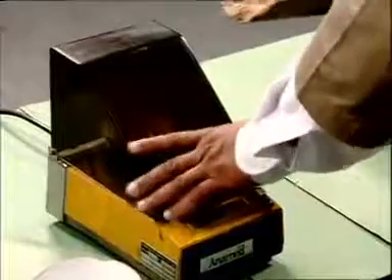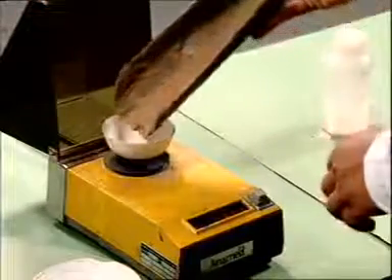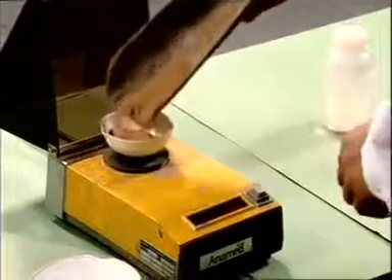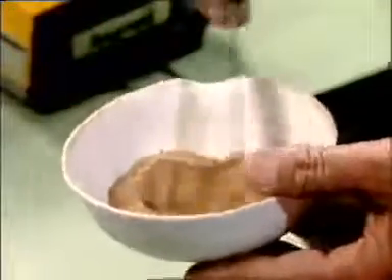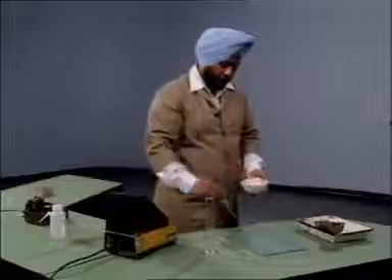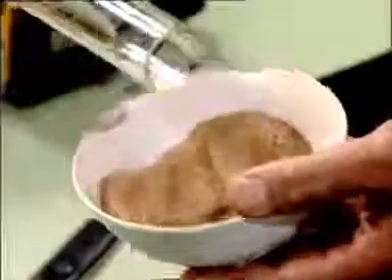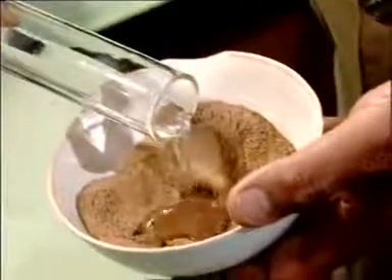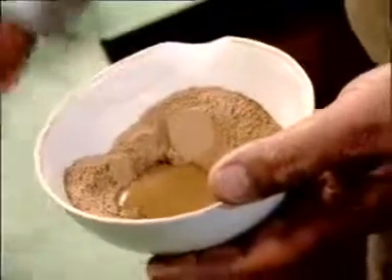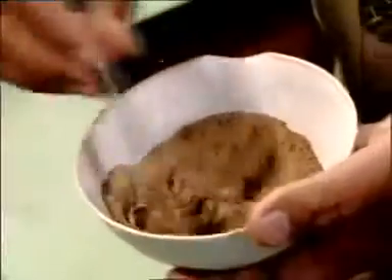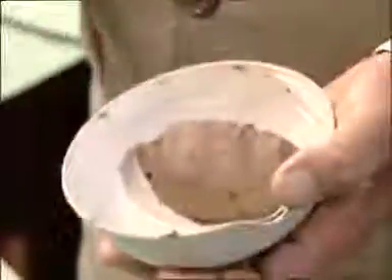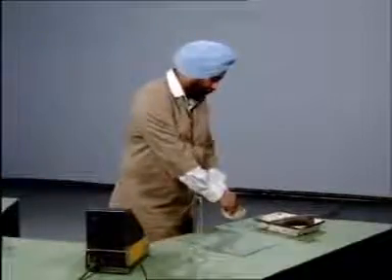To begin with, take about 50 grams of soil sample passing 425 micron IS sieve from the prepared sample in the evaporating dish. Now add distilled water to the soil sample and mix it thoroughly so that the soil mass is plastic enough to be easily molded. Prepare a ball weighing about 8 grams out of this soil mass.